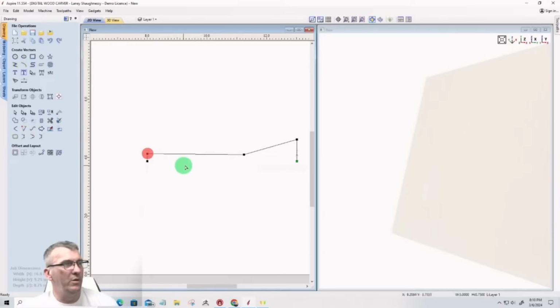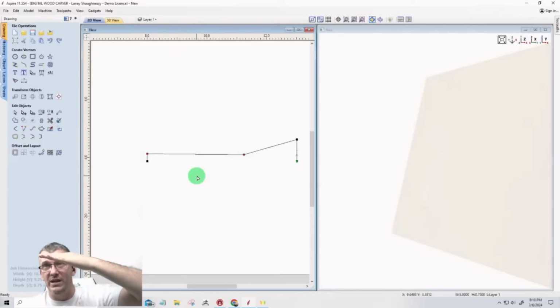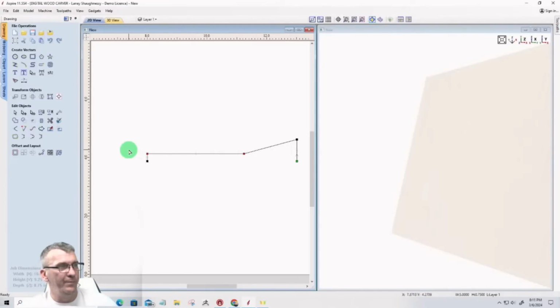What I want to do is I'm going to use node editing. If I select this node first, that's the node I want to align to. And I select this node last, that's the node I want to align. If I hit the letter Y, it'll straighten those nodes out and even with one another up and down. If I hit X, it goes left to right. I want to hit Y to make a straight line there. And then I want a Bezier curve.